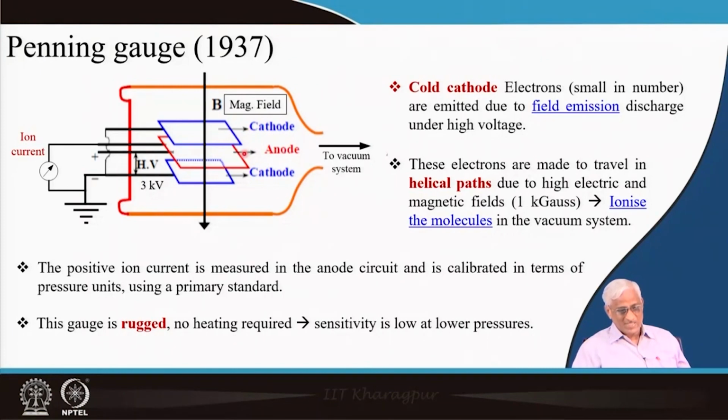Okay. So, this anode is connected through an insulated bush here, which I have not shown, but there will be an insulated piece here. This collector terminal will be insulated from the body. If it is glass, of course, anyway they are insulated, but otherwise you have to insulate this body, which is connected to the positive voltage, a high voltage of 3 kilovolts. This is a ring type of electrode, and there is a magnetic field perpendicular to these cathodes.